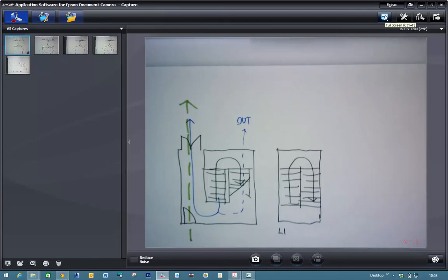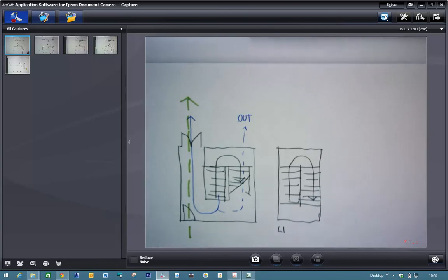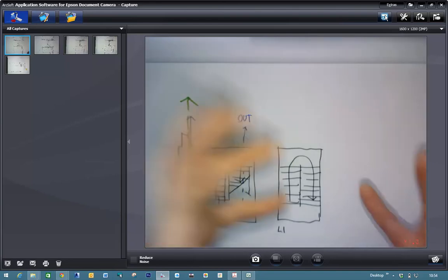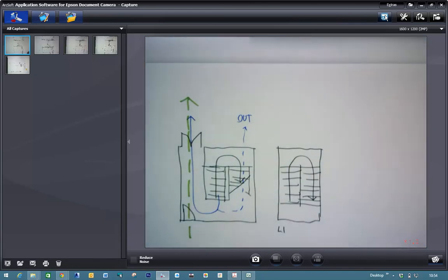Right. Any questions? If you've got lower ground floors, do you have to have another set of protected stairs? Otherwise, people could just continue going down. Basement floors. Yeah. No. As long as you've got adequate signage, you can have the same stair going down, coming up, and people need to be alerted through signage that this is the floor to exit. Yeah, it's a good question. I mean, basement design, I've not covered basement design. It's a bit more involved. You could look that up. I mean, not that involved, but there's a little bit more to it.